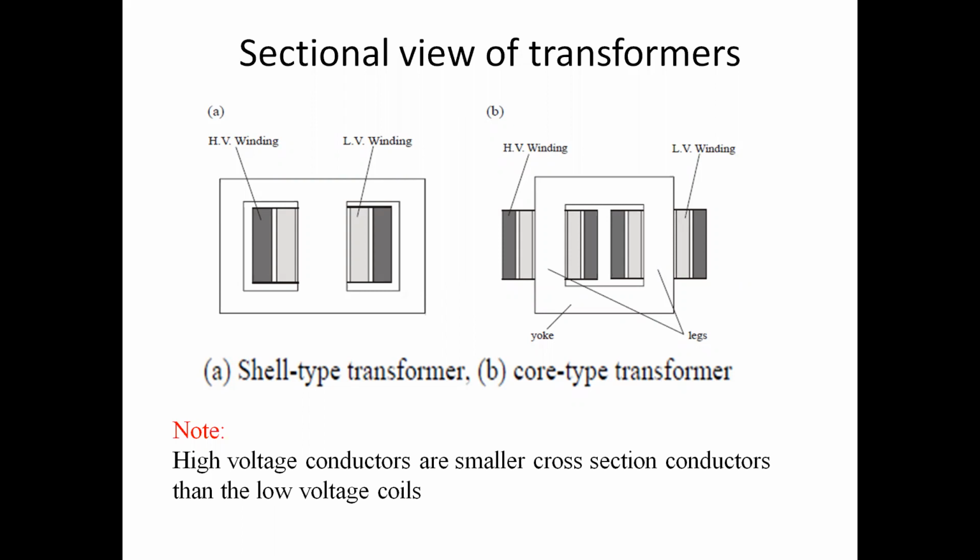There are 3-4 reasons I will tell you. First, HV means high voltage, correct? So if it is outside we can properly insulate, like it may be 6.6 kV or 11 kV. Second, the tap changer.